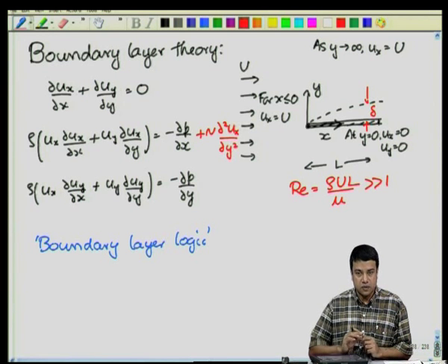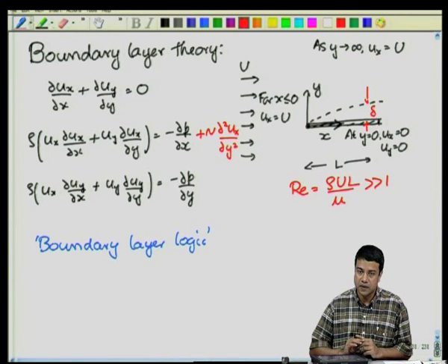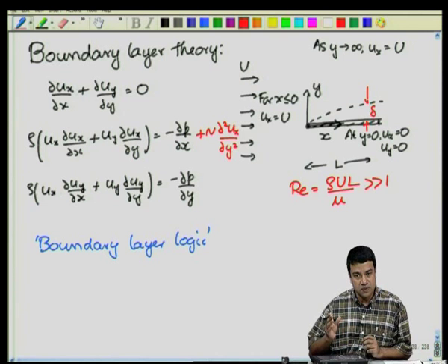Previously, I had assumed when I scaled these equations to get the inviscid equation that the relevant length scale both in the streamwise as well as the cross stream direction is the length of the plate itself. On that basis, I had simplified the equations and then there was a prefactor of Re inverse multiplying the viscous term, and therefore, I had neglected those viscous terms.